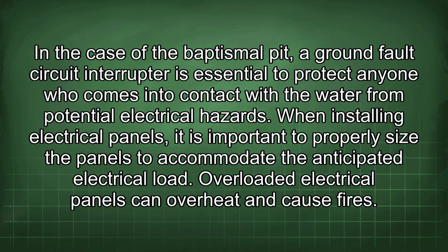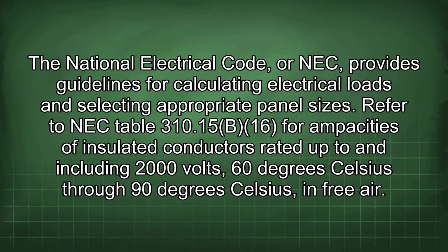When installing electrical panels, it is important to properly size the panels to accommodate the anticipated electrical load. Overloaded electrical panels can overheat and cause fires. The National Electrical Code, or NEC, provides guidelines for calculating electrical loads and selecting appropriate panel sizes. Refer to NEC Table